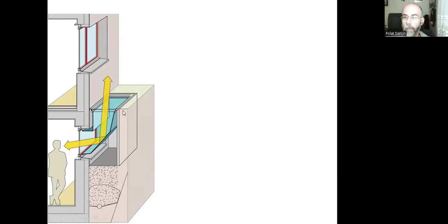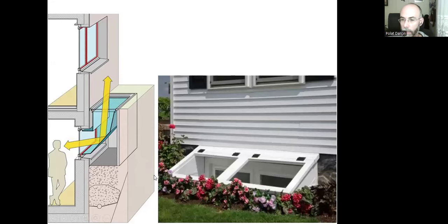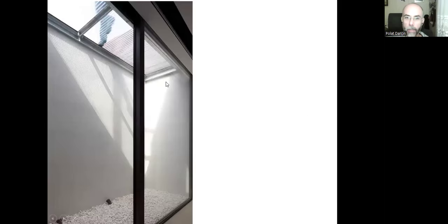So we can create a tiny shear wall around this earth window, so that the tiny shear wall will hold the earth and water, and it can provide clean air and natural sunlight for our basement floor, something like this. That's what we call a window well, an areaway. In Turkish, we say krangles. Krangles is a French word. It means court anglais, English court or something like that.